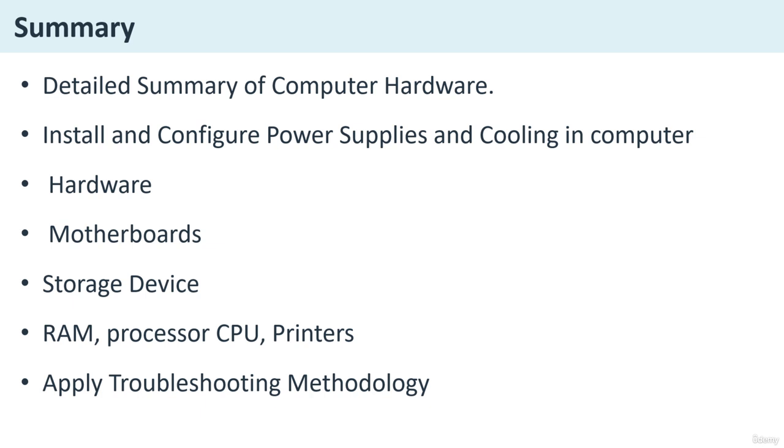Now, thermal paste application techniques. Most common and effective is the pea-sized dot. The second one is the X method, which spreads paste evenly for larger CPUs. Then the spread method, which is manually spreading with a card, with a risk of air bubbles.